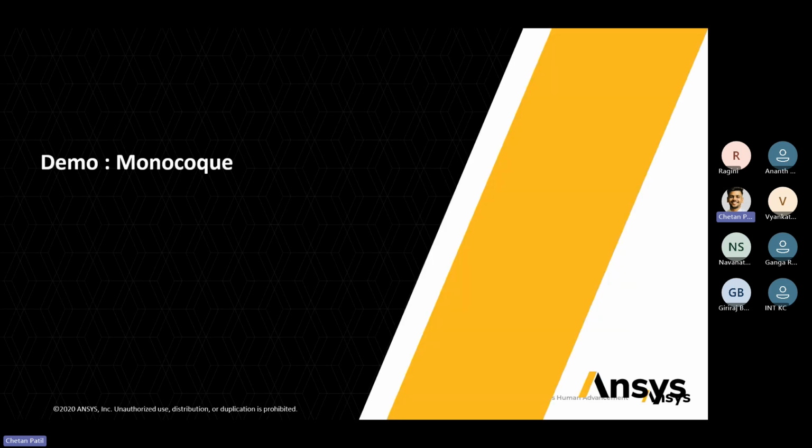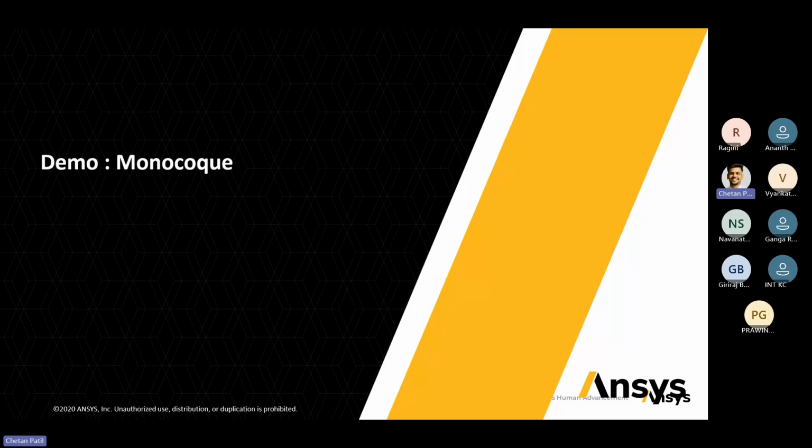So this demo that we are going to perform over here, we are not going to go much into the theory part. Over here, we'll directly jump into the demo itself. We are going to make use of a monocoque model, that is a Formula SAE monocoque. On that monocoque model, we are going to apply composite layups and definitions so that we can increase the strength of the model with respect to the structural conditions that we are going to provide. We are also going to see how we can do a parametric study for a composite model that we are going to create.